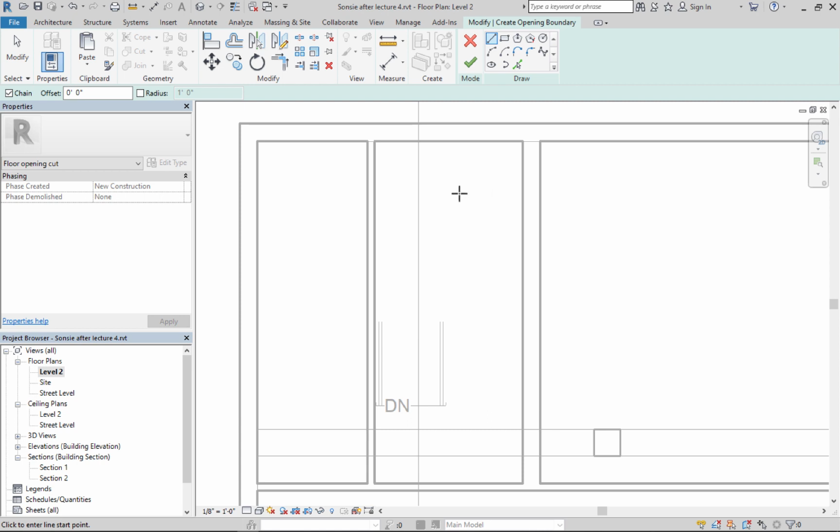And in fact, the correct way to draw an opening for a stair is to have the entire shaft of the wall go up to the roof, and have it be open. If you think about it, when you're inside a stair, you see that interior wall, and it's pretty continuous. So what I want to do is draw a rectangle from one corner here all the way down to the other.